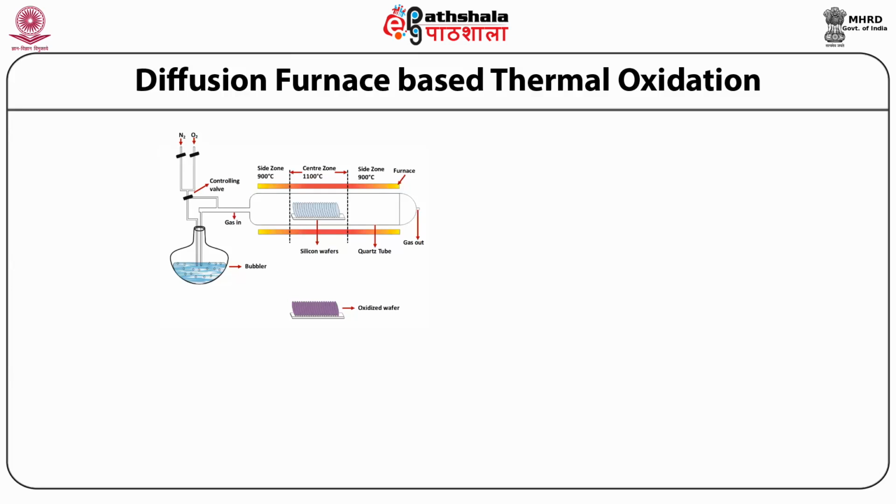The temperature is raised to 800 to 1100 degrees Celsius in 3 different zones to speed up the process. The center zone is naturally limited to materials that can be oxidized, and it can only form films that are oxides of that material. So the gas is purged into the thermal furnace from one end.